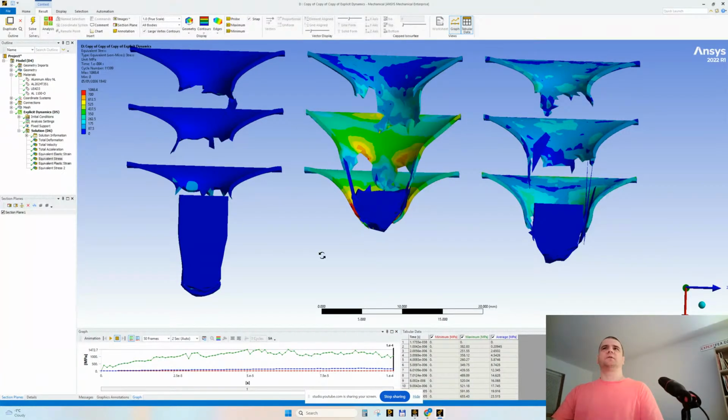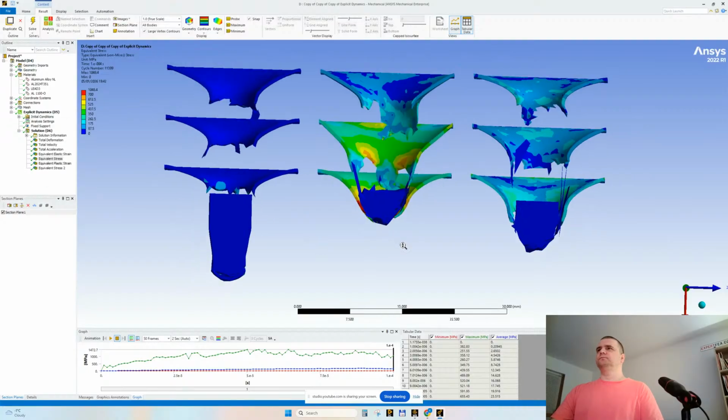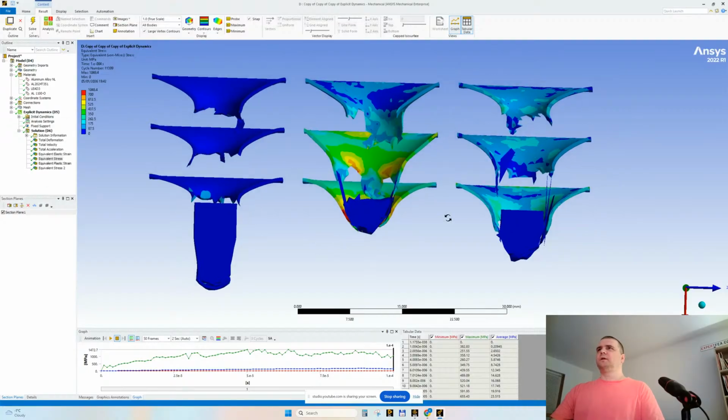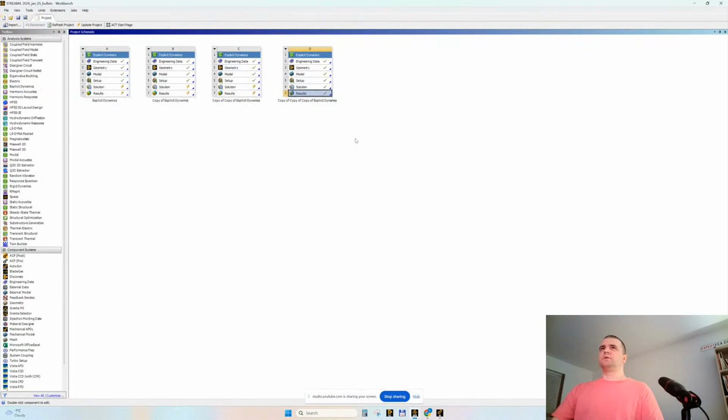What I wanted to run, I would like to run this scenario with a finer mesh on the plates, only this scenario, yes? So this is extra according to my taste. And I want you to see the 2 elements per thickness in the plate. This is what I want everyone to see. This is very nice. Duplicate.